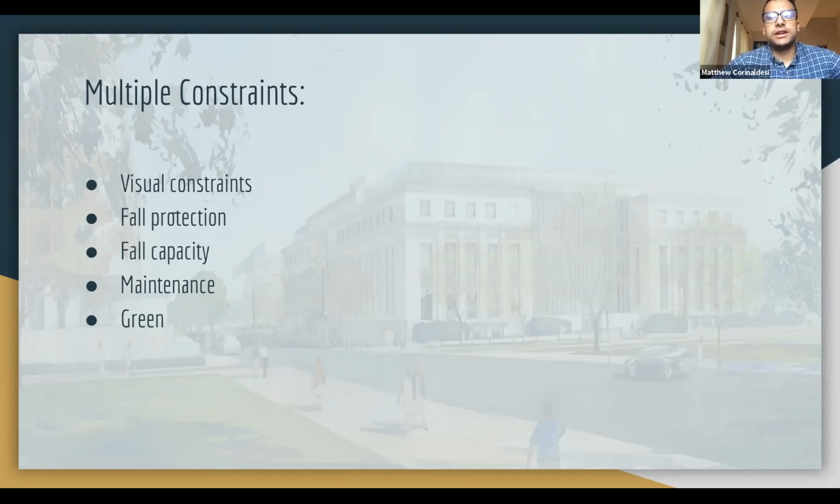Routine maintenance is needed to keep the garden roof pristine and in good health. The three main areas of maintenance are watering, weeding, and plant care. We chose to use an extensive green design so that there would be little maintenance needed, and we chose plant species that do not need supplemental irrigation. According to the DC DOE Stormwater Management Guidebook, the roof should be inspected by a qualified professional twice a year during the growing season to look for leaks and drainage problems.